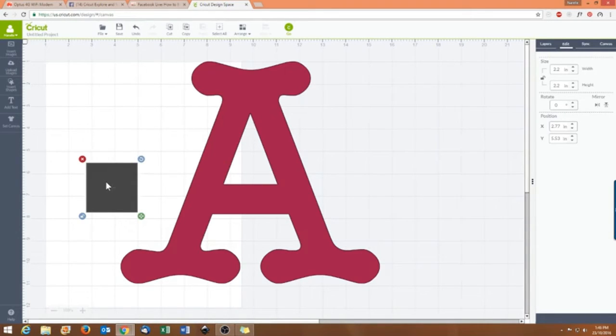If I want 1 inch in between and I want the two horizontal bars, then I need to also add the amount of space that those two horizontal bars will take up. So I make my horizontal bars 1/4 inch, and if I want 1 inch in between the letter, that means I need 1 inch plus 2 lots of 1/4 inch. So I need this square to be 1.5 inches in height. So I'll change that over here.